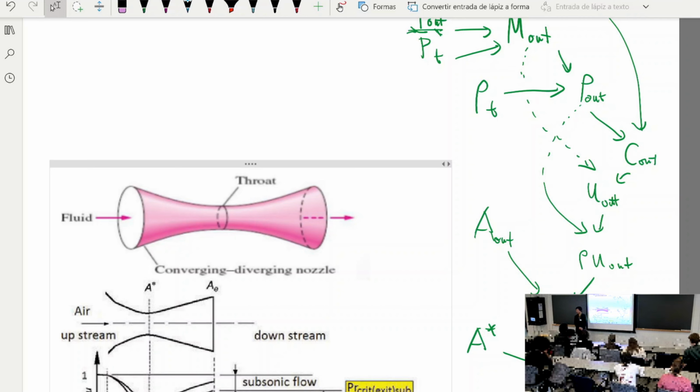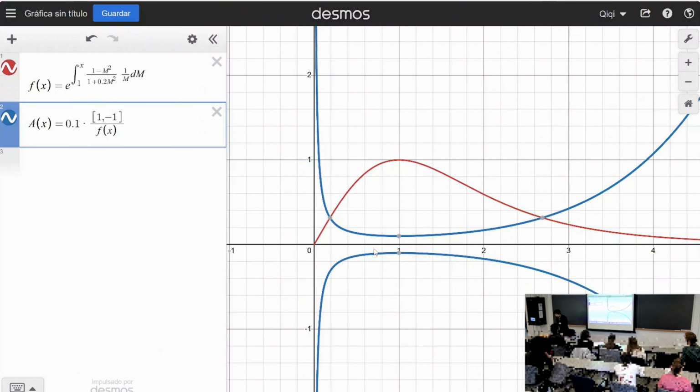So this is assuming a subsonic nozzle. So how do you find out if the nozzle is subsonic or not? Check if the Mach number is 1 at this throat. Check if this number, rho u, is below or above the maximum possible.